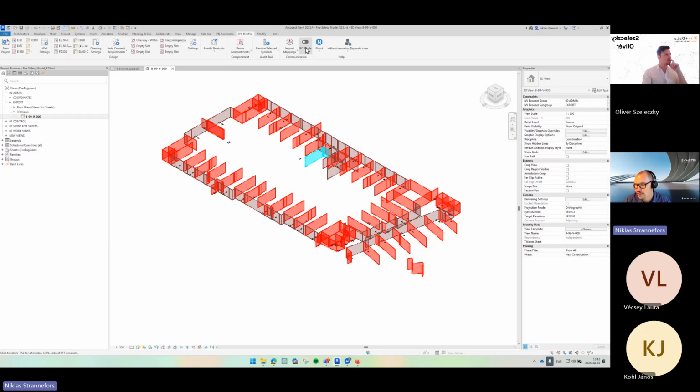Oh, and that is ArchiCAD mode, so don't grab a Tekla model and assume it would work. I haven't tried it to the full extent. It worked with some walls that I tried, but I don't guarantee anything. Depending on which software we export IFC from, the length, height, et cetera, are in different places in the IFC to create those volumes. So that's the background of it.